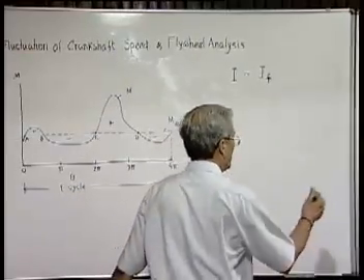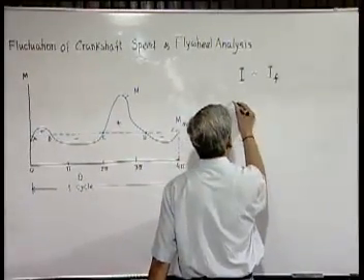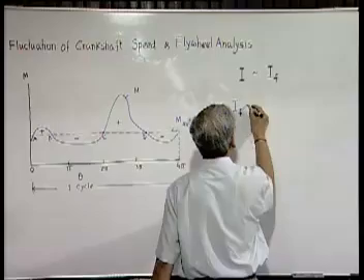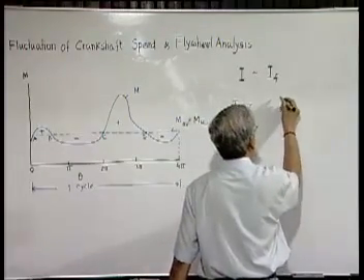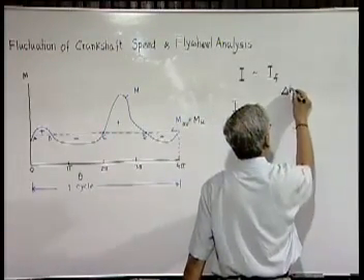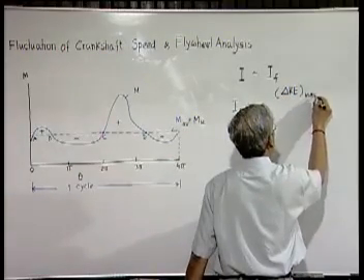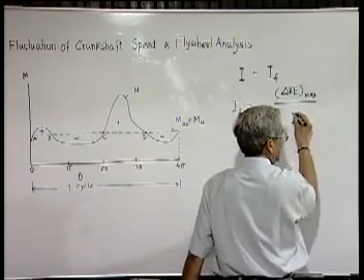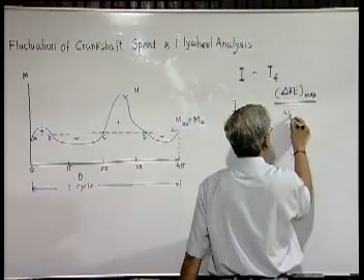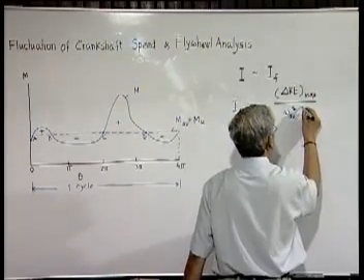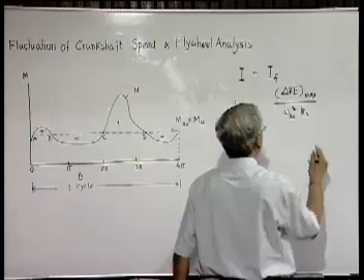And therefore we can now find out that approximately we need a flywheel whose order of magnitude is found out from the maximum fluctuation of energy divided by omega average square into the coefficient of fluctuation.